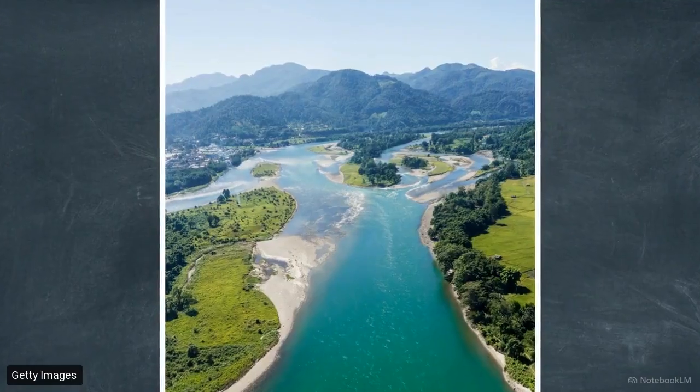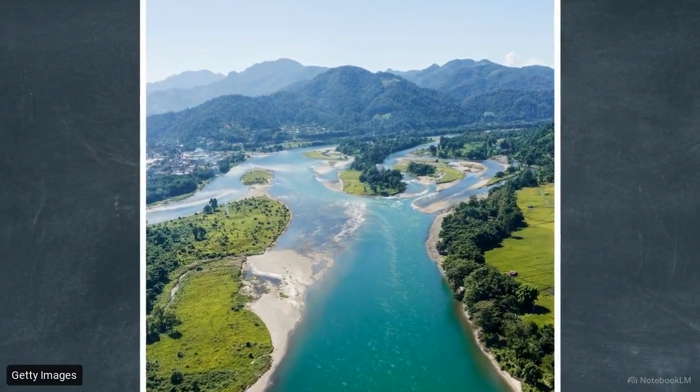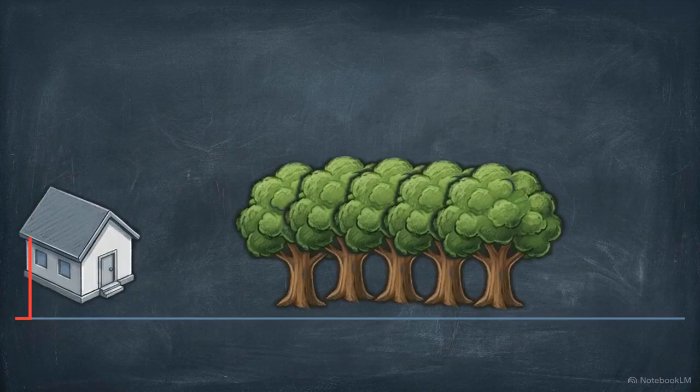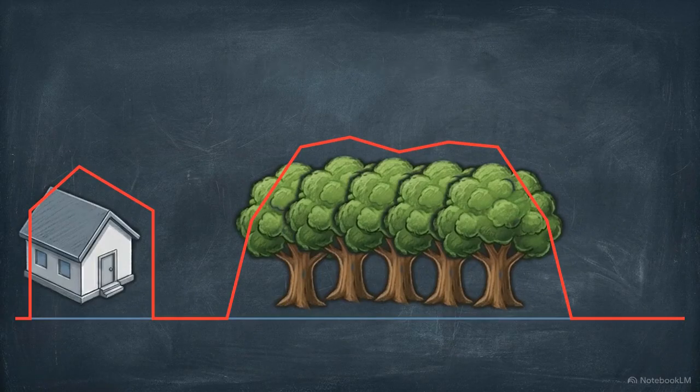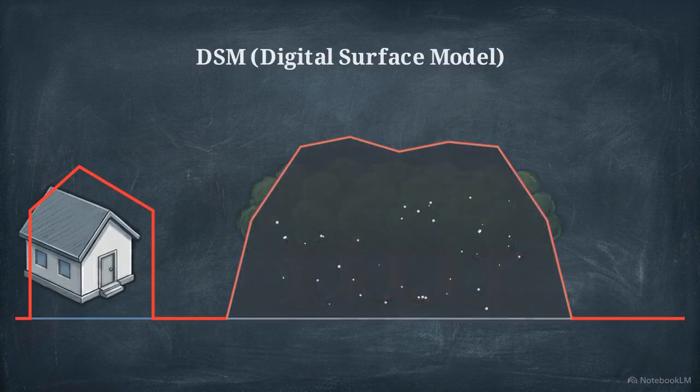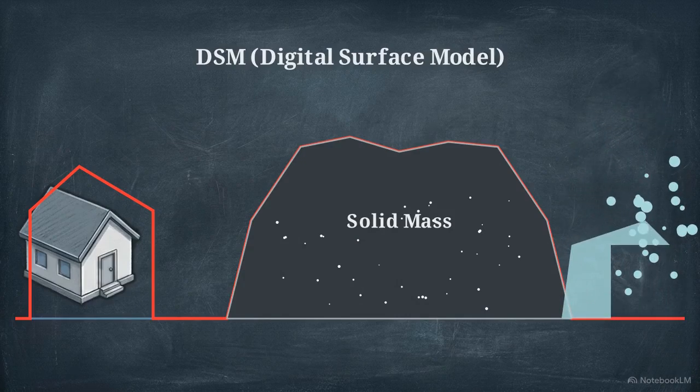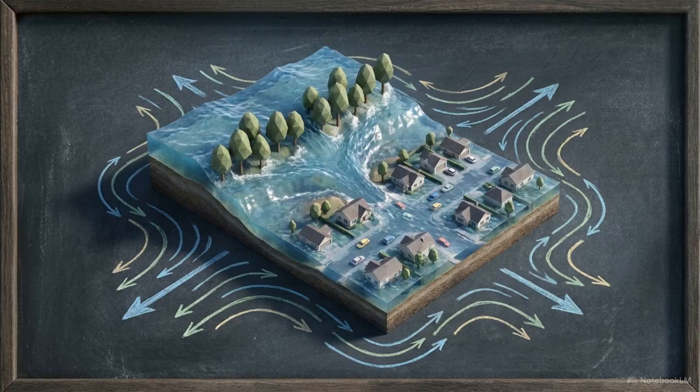Gravity requires a hyper-accurate three-dimensional canvas to route that water correctly. Standard drone photogrammetry is insufficient. It generates a digital surface model, which wraps the tops of tree canopies and roofs rather than the earth below them. Feeding a surface model into HEC-RAS causes the software to treat a dense forest as a solid, impenetrable concrete wall, routing digital water completely in the wrong direction.